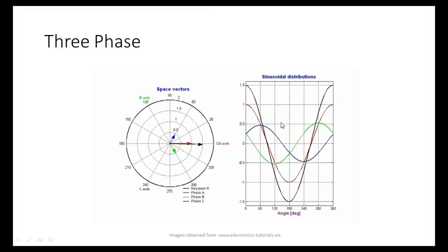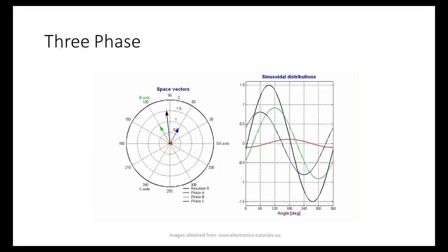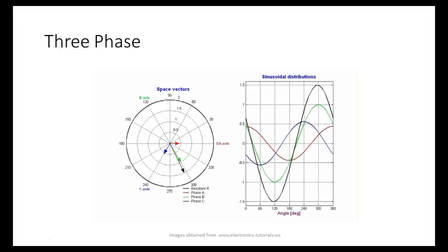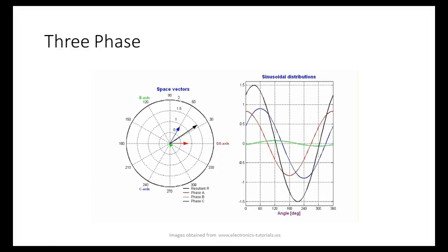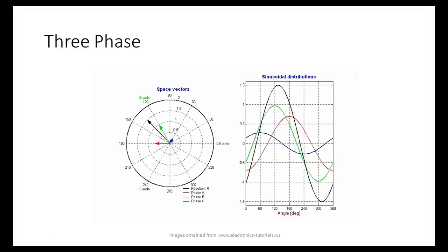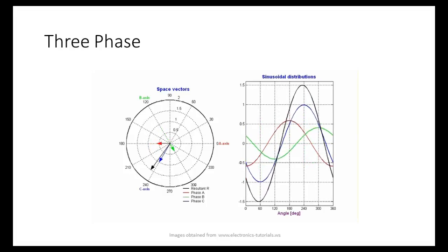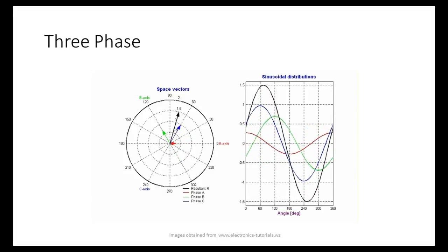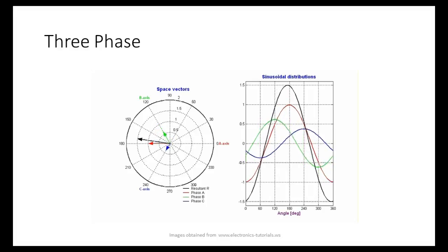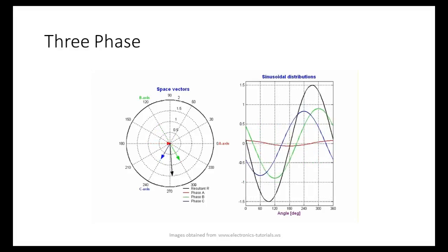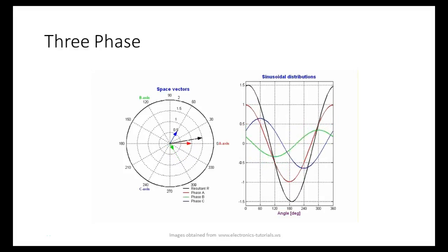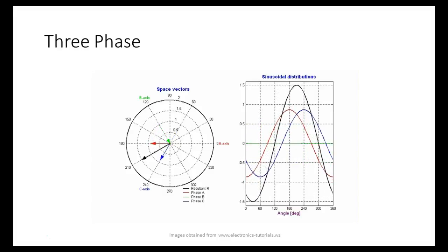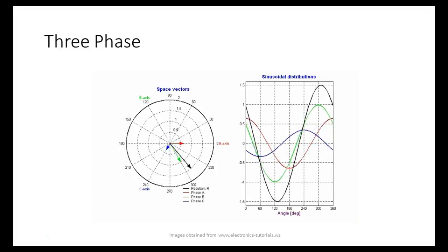So how do we change the direction of a common three-phase motor? Industry standard: change L1 and L3. But literally, how can you reverse it? You've got to watch out for those kinds of questions. They do that on the Siemens test. It says, how can you reverse a three-phase motor? They don't ask you the industry standard. Well, you can swap any two phases, right? You could literally swap 1 and 3, 2 and 3, or 1 and 2, and the motor would reverse.